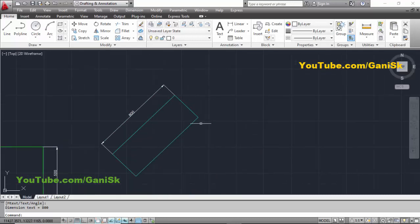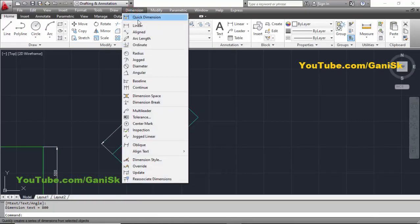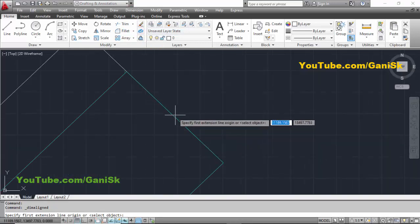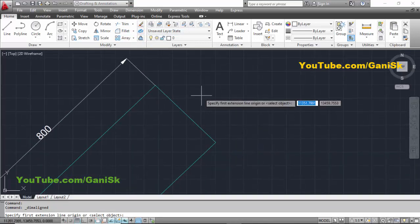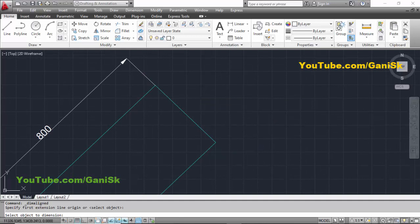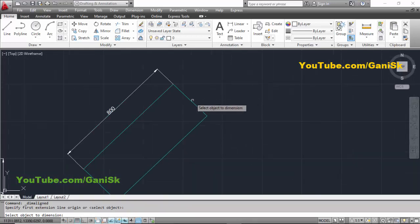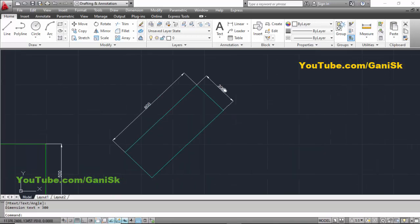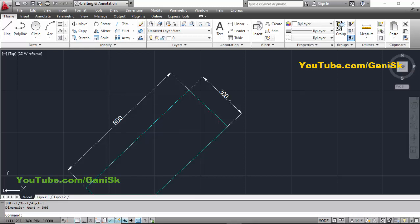Now we're going to check the width, so click on dimensioning and select this aligned dimension. If you want to select the edge, you need to press enter once again. Now you will get this little rectangle cursor symbol. Now select this edge, then drag and place the dimension here by using the left mouse key.